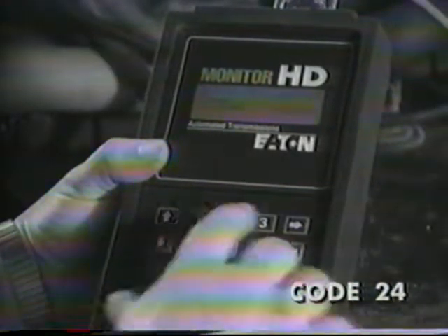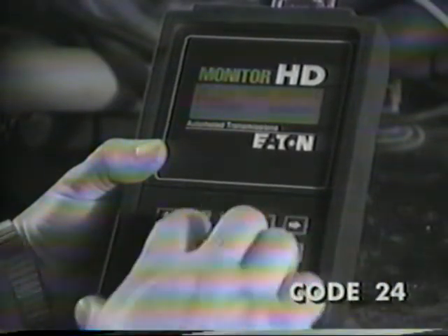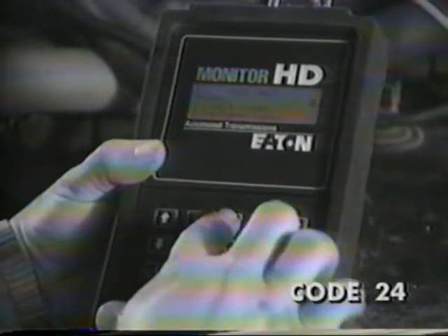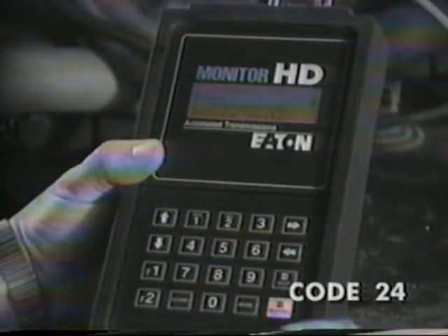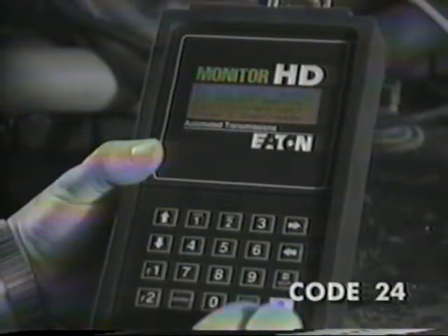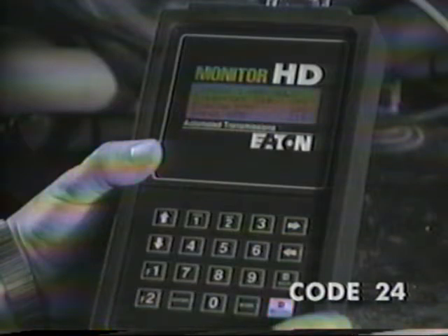Now, if everything checked out, you'll need to connect the diagnostic handheld tool. Select 1 from the main menu. Then select 1 for CEEMAT. Select 2 to select Perform Test again, and 6 for hydraulic test. Now 1 to select the interrupt test, and 1 again to confirm that the vehicle is in neutral and the parking brake is set.